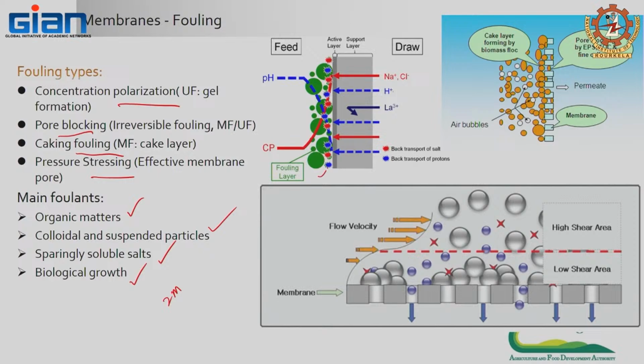This shows how the fouling layer can work, and how it is clogged between the membranes, cake formation, or because of air bubbles, and then how it can impact the membrane. So, membrane geometry also plays a vital role in this. Spiral membranes and ceramic membranes are much better, though quite expensive, as well as membrane fouling.